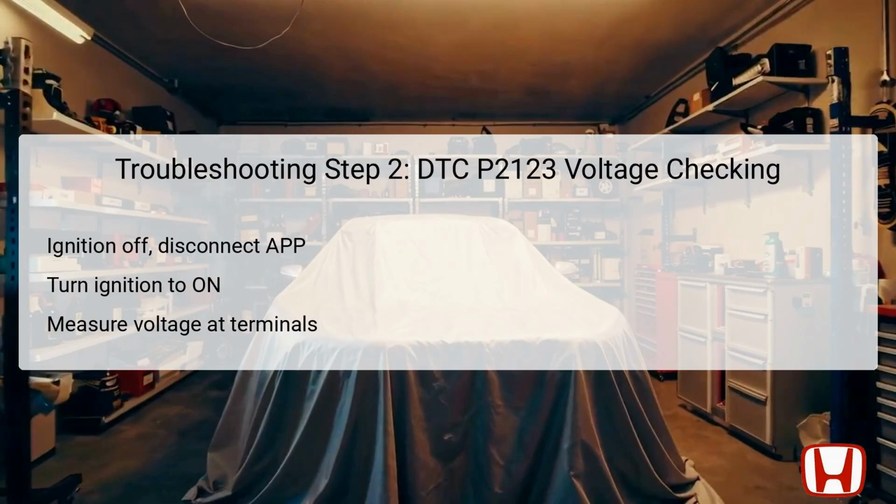In this step, after ensuring the malfunction is not intermittent, turn the ignition switch to the lock position and disconnect the APP sensor's 6-pin connector. Then, turn the ignition switch back to the on position. At this point, using a multimeter, measure the voltage between the APP sensor's connector terminals, specifically terminals number 2 and number 3. It is critical to observe if the voltage reads around 5 volts.